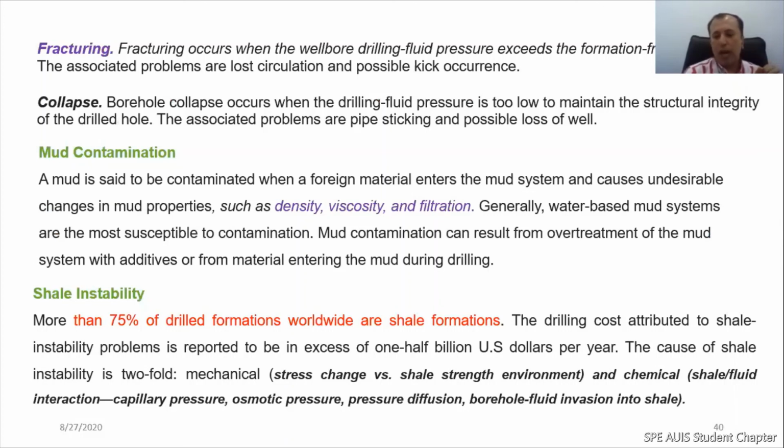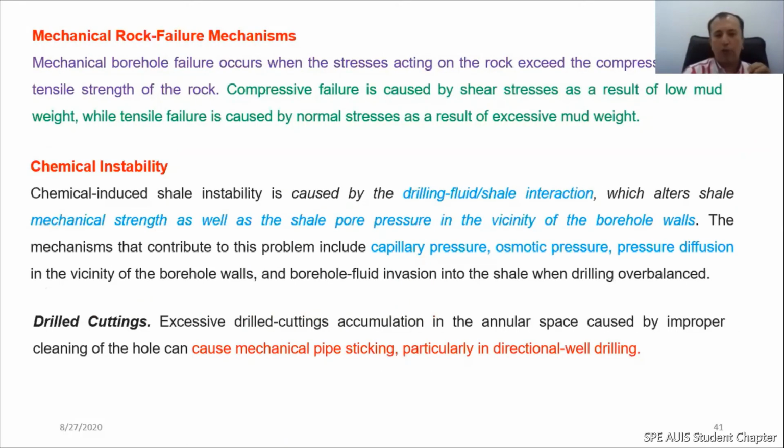That clay, when it touches water, will expand, will swell. When it swells, it will stick with the shaft and we will not be able to take the shaft out from the boreholes.